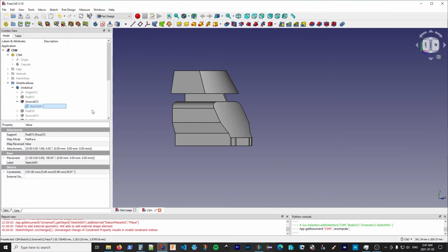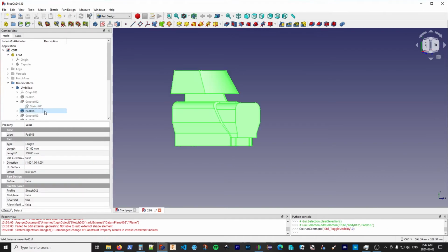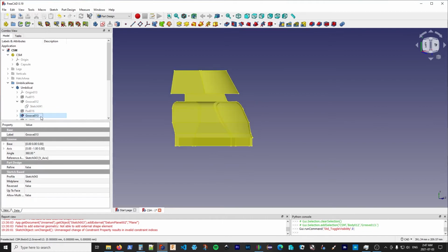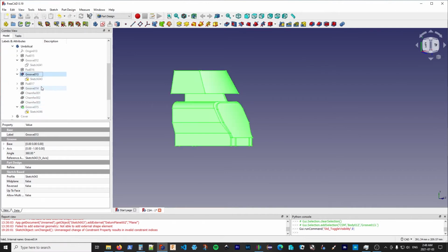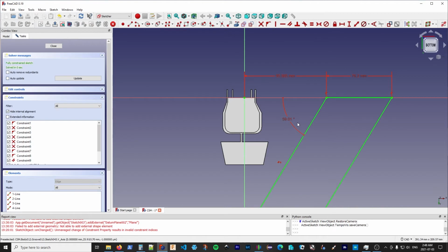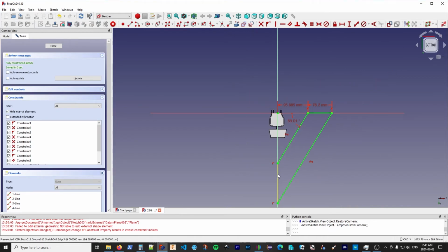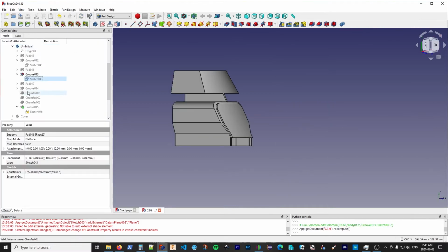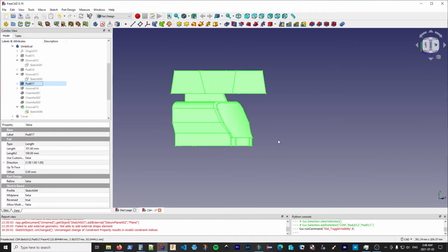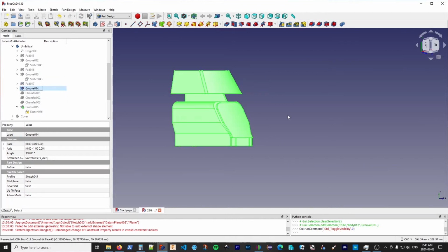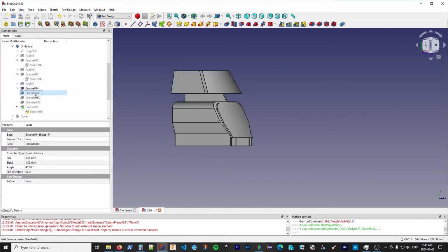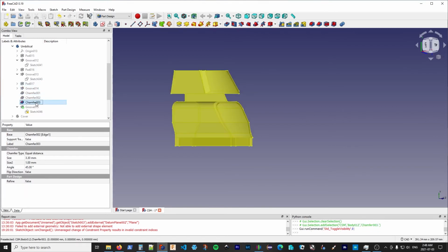And we can do this multiple times and keep adding features to it. So we add another pad, groove it again in a similar way, and now we've got that conformal shape. Okay, so again, looking at the sketch, it's going to be revolved around the vertical axis, and it's going to do a 360-degree sweep and give it that rounded edge that we need to make it part of our project. Okay, so we can keep doing this. So we add another piece on the top, add another groove. Okay, chamfer that top piece a few times.